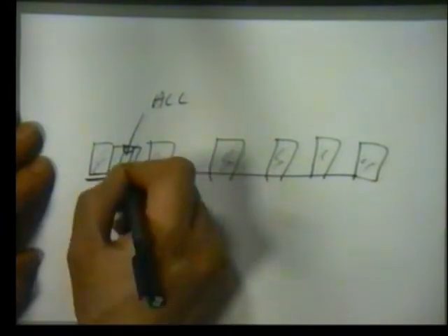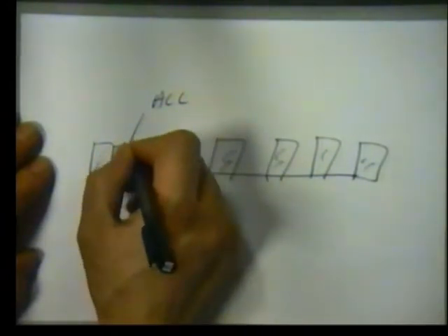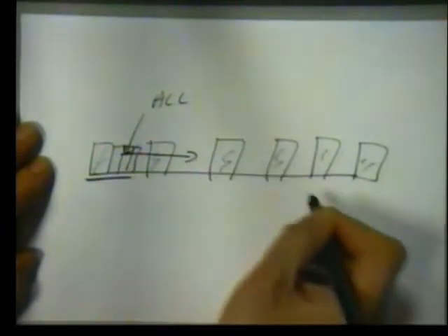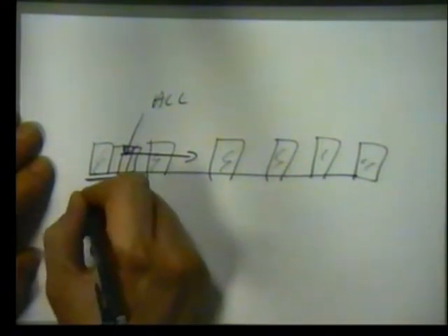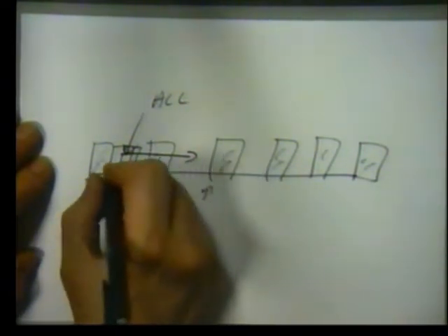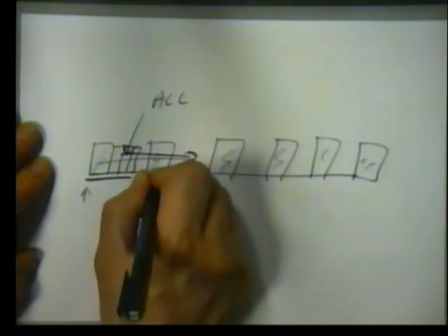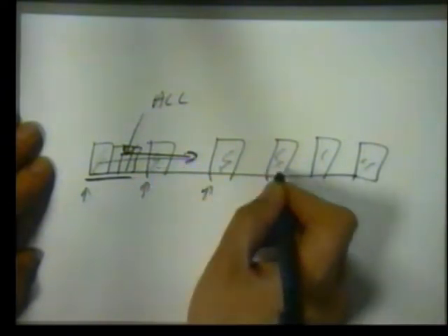It's got to be. If all your other interrupts were to spread it out and take longer than the rate of arrival of the fastest interrupt, you would displace the fast interrupt from its required time slot. So the rule is the sum of all of the execution times of all of the interrupts in the system must be faster than the rate of arrival of the fastest interrupt.